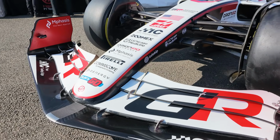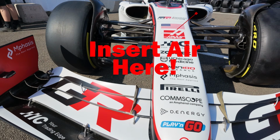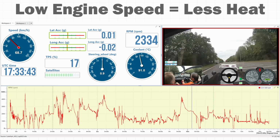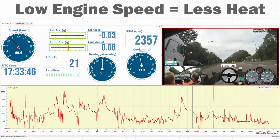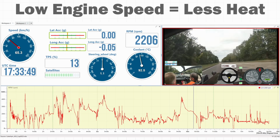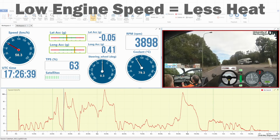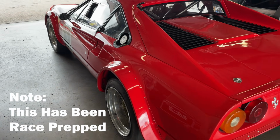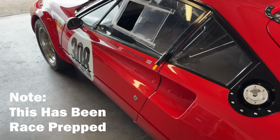Now this has a massive impact on the amount of heat that is being generated. In a road car, over an average period of time, you've got a lot less heat. And heat transfer is time-based, so we can have a cooling system that is designed for quick acceleration off the line that might not be able to handle that non-stop. There's a capacitor-style effect of water. We don't need to size the cooling system of a road car for maximum power output or maximum RPM output. And one of the common issues that we have if we take a road car that's designed for the road and put it on a racetrack is it'll often overheat. Because in a race car situation, you're going to be using much more of that power more of the time.